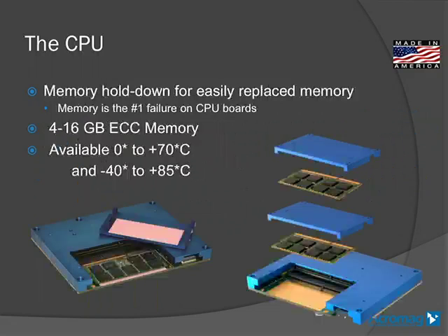So one unique feature that we have on the CPU board, besides the pieces that I've mentioned, is that we looked at this and determined that because memory is the number one failure on the Com Express boards, in most cases you look at offerings for industrial or heavy ruggedized applications, they typically solder them in place. We came up with and developed and have tested a fastening and fixturing mechanism that's shown here.